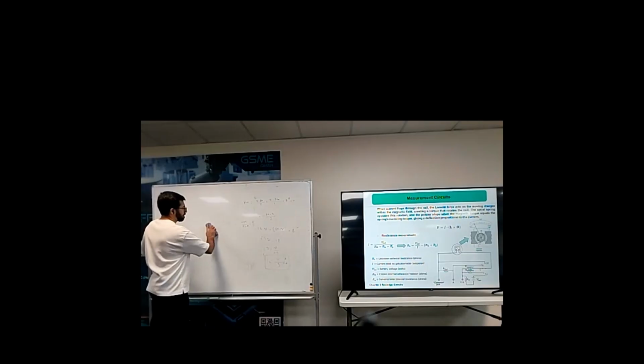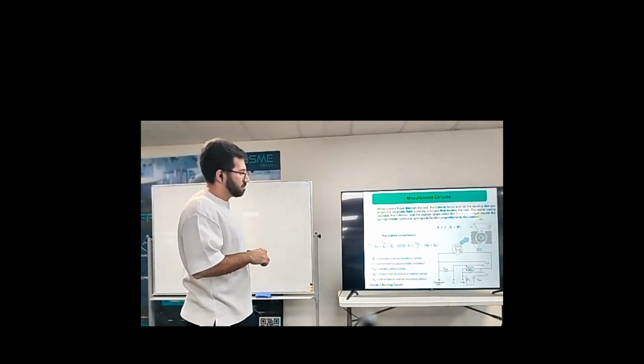Which means if I want to show you the equivalent circuit of measuring a resistor, suppose we put the selector in ohm. We connect the resistor that we want to measure to this and this jack. So we have this resistor that we are looking to find here, which is connected to here.